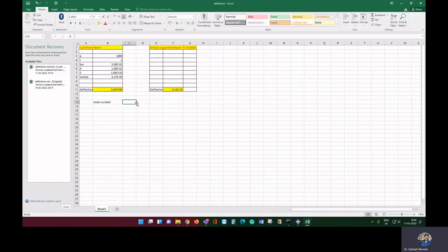And here you can write this is your deflection. Now we write the node number as 20, then we have 500, then we have 2000, and then we have 10,000 elements, and we have noted down the deflection, that was 2.45, then 2.45, and then we have 2.83 e to the power minus 2, and then we have 2.656 e to the power minus 2.